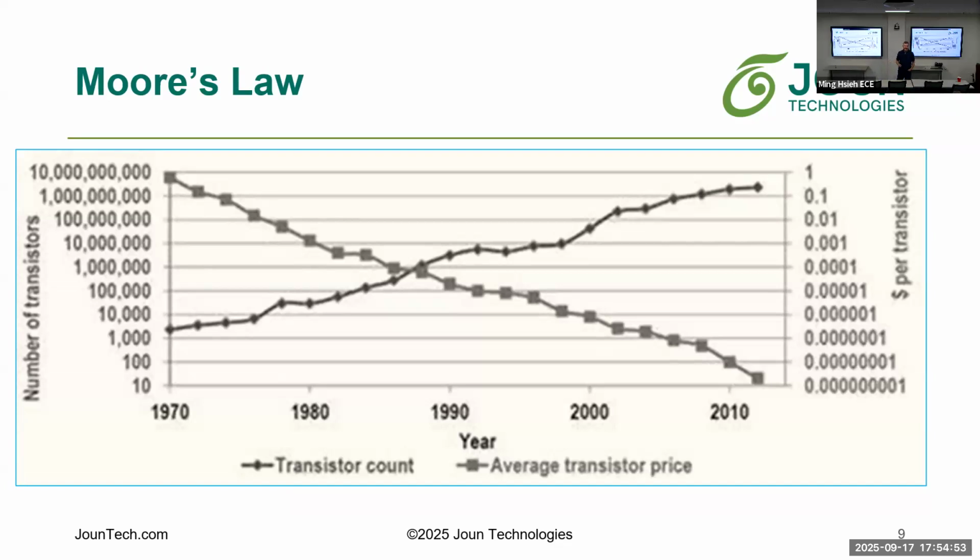He basically said that the rate and pace of innovation for semiconductors is such that roughly every 18 months, you can double the number of switches, transistors, that are on a given area of silicon. You can also use it in a different way by saying you can significantly reduce the area a given number of switches will take up. And so depending on whether you're trying to drive for more performance, so you put more switches down in that area, or if you're doing a cost reduction, which says, I want the same number of switches, but I just want them on a smaller piece of this wafer because it'll cost less. And it's used both ways in the industry.